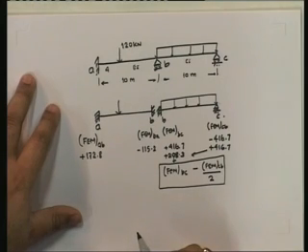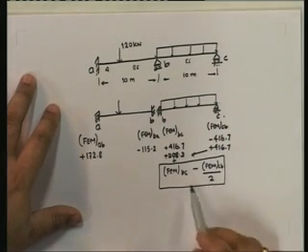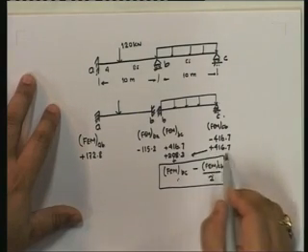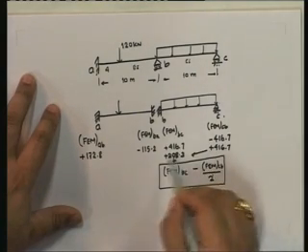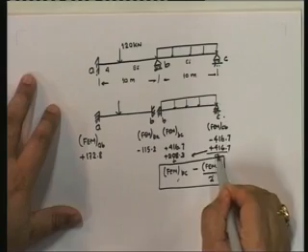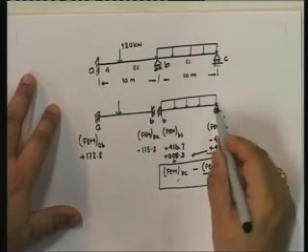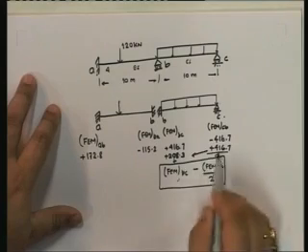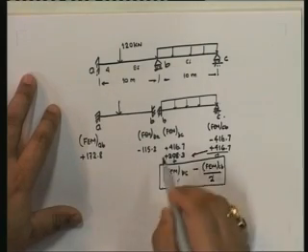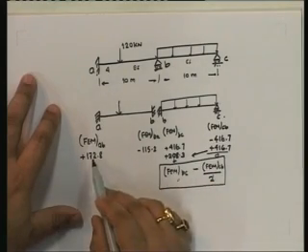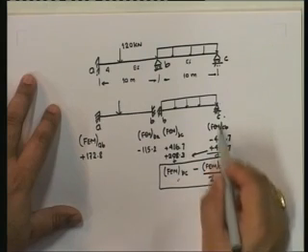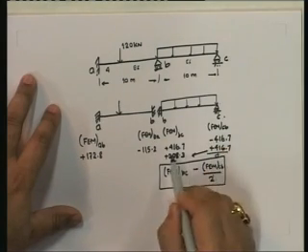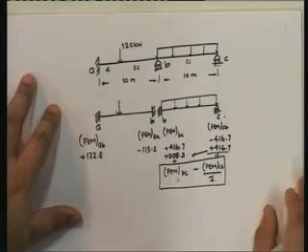You see, this is almost exactly like that, and once I release this, that's it. Now this has gone to 0 and it will never come back again because this is a roller. We can do this even with fixed end moments: we compute the fixed end moment as if this was fixed, then do the balance over here, put it to 0, transfer it over here, and then solve the problem.